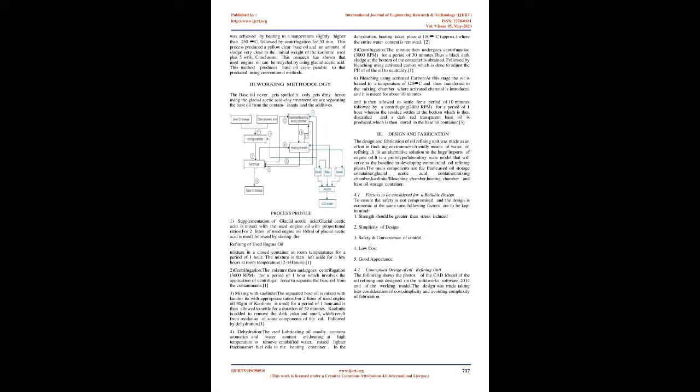Bleaching using activated carbon. At the end of the acid treatment step, if the acidic oil is to be bleached using activated carbon (charcoal), the same procedure for bleaching using industrial bleaching earth is also used, except that the temperature was increased and maintained at a range of 130°C–140°C. The same amount of activated carbon as that of the industrial bleaching earth and hydrated lime was used.